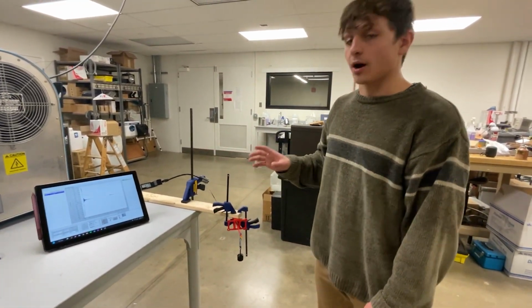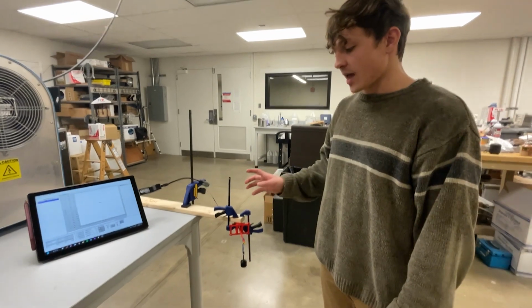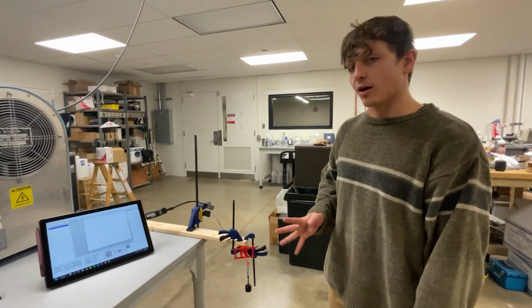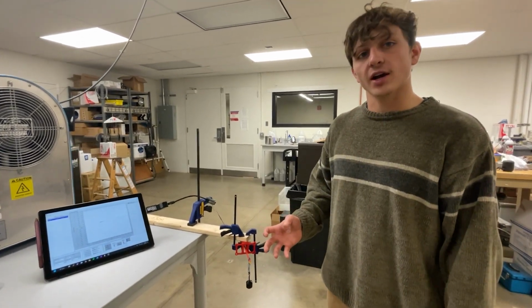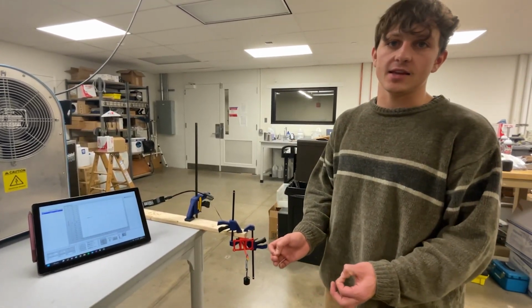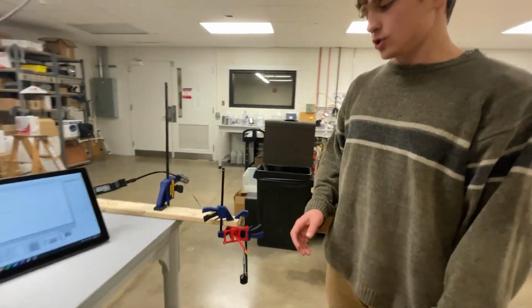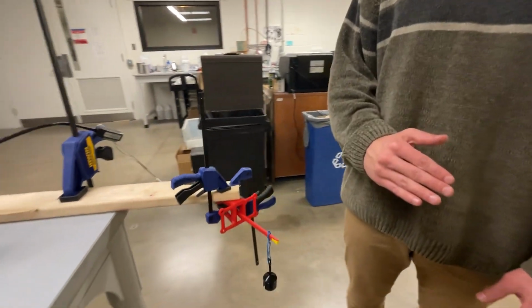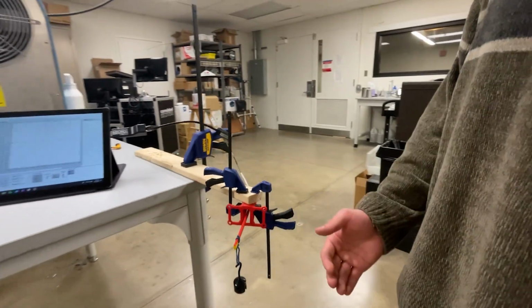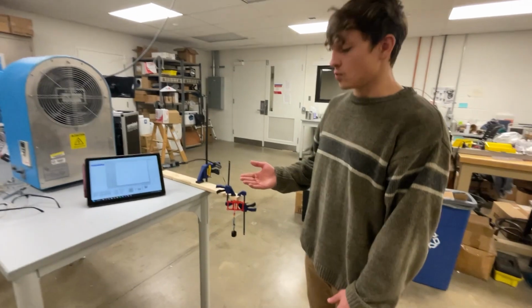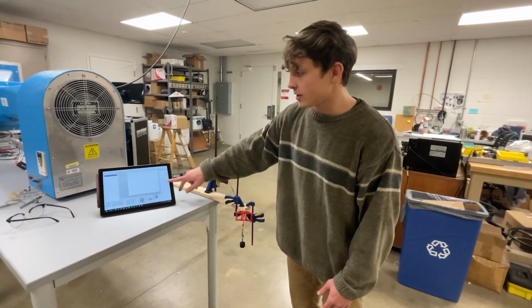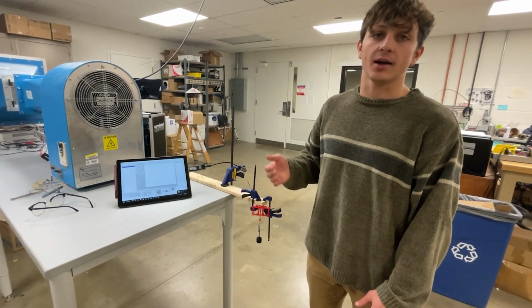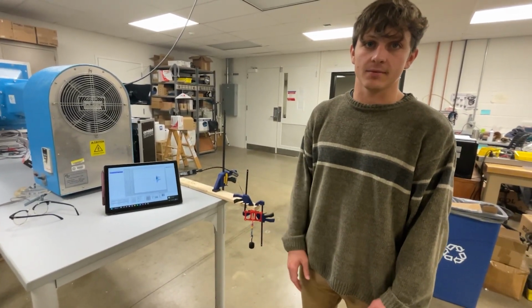and going through our data between applying the load directly to the load cell and applying it through this lever arm, we were within 4% of accuracy, which was pretty good for us considering that it's really hard to get the measurement exactly right. So doing our calibration this way allowed us to reduce the amount of assumptions we were making and have higher confidence in our calibration, which is what we used to determine what output corresponds to what level of force. So doing it this way really allowed us to have a lot of confidence in our method.